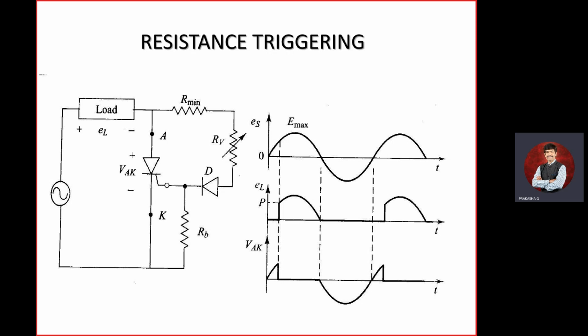So what we need to do is measure at each element whether the input is coming properly. Sometimes the result is not going to the circuit because they are not grounded properly. There should be a positive and also a ground point, a negative. Sometimes we forget to connect the ground, so we are not getting the power supply data.